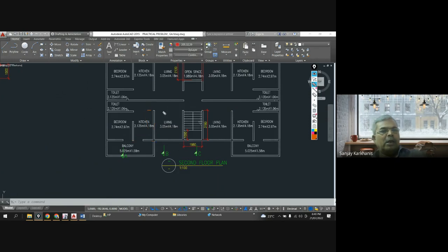and based on that they say don't go for whatever loading that we are asking you, right? See, live load intensity, what live load intensity you are providing over here per kilonewton, you are considering 3 kilonewton, or let's say in a residential building you are considering 2 kilonewton per square meter, right?